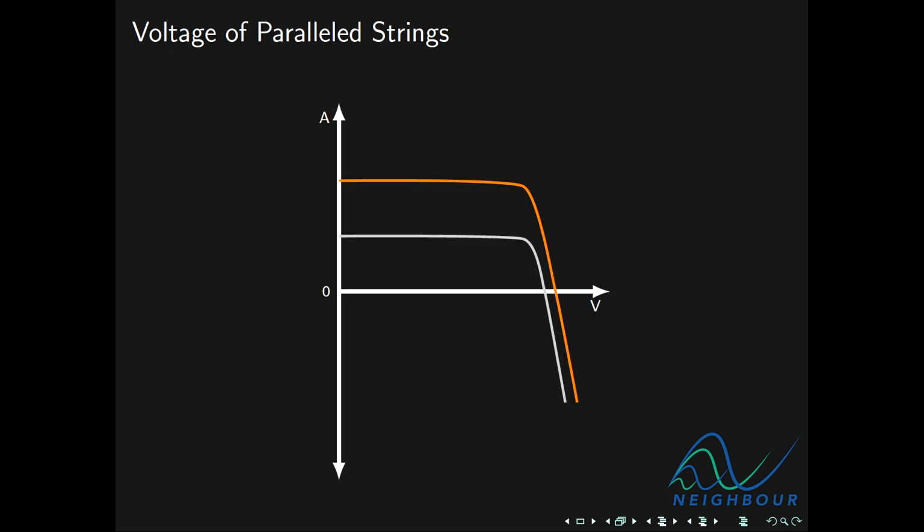And let's now extend it beyond the open circuit voltage, such that we're extrapolating it from the maximum power point. Again, at open circuit voltage, there's no current running through the module. Slightly to the left of the open circuit voltage, the module is acting like a generator.